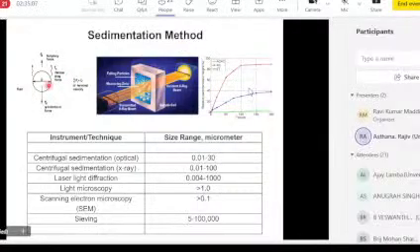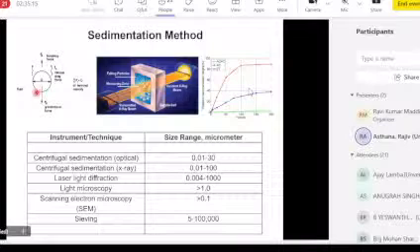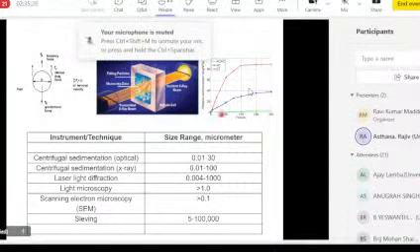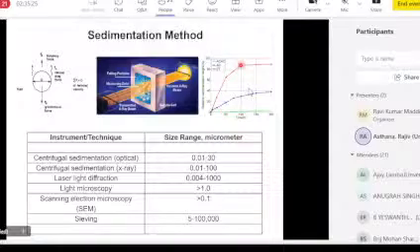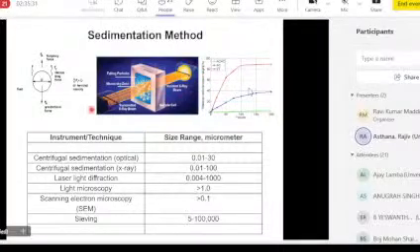The problem is the powders are extremely fine, so they will take a very long time to settle even a short distance. So instead of using gravity, people use a centrifuge to speed up the settling process. When you centrifuge a suspension, you can figure out the size of powders by using a light source. The incident light and transmitted light intensities can be calibrated to give you the size range. Different techniques have different sensitivity for size range.